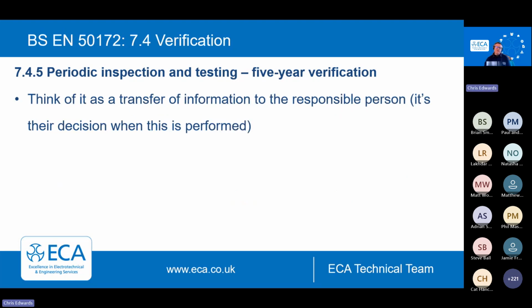Now, with regard to this 5-year verification thing, there would be an assumption to pair it with an EICR type thing. Now, whilst there are loads of similarities, this is not a pass or a fail type thing. We're not issuing a certificate that says unsatisfactory or satisfactory. It's not like that here.